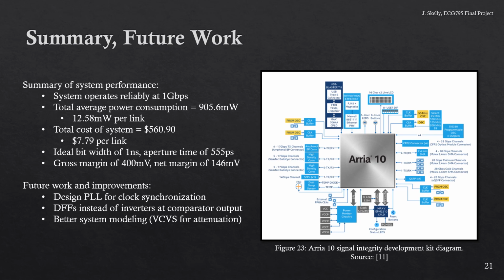From an ideal bit width of 1 nanosecond, we are left with an aperture time of 555 picoseconds due to timing uncertainty and a worst case rise time of 130 picoseconds per the transceiver speed grade given in the Arria 10 datasheet.